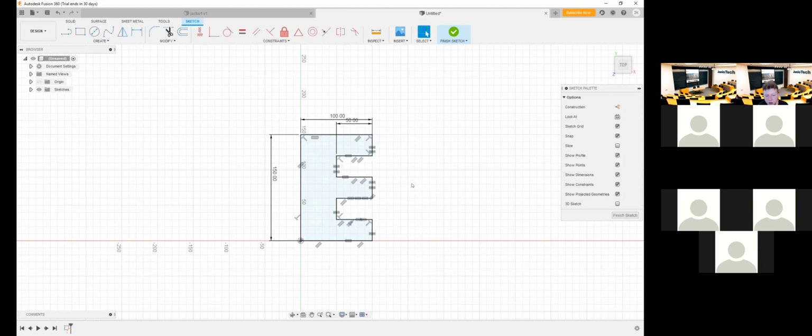There you go. Now your E is fully black. I think this would probably make it look a little better. Beautiful. All right, guys, so this is exactly what you want. You want your E to be fully black. And Jacob, notice this, if you drag on any of the points, any of the lines, nothing happens. Your E won't budge. That's because it's fully constrained.